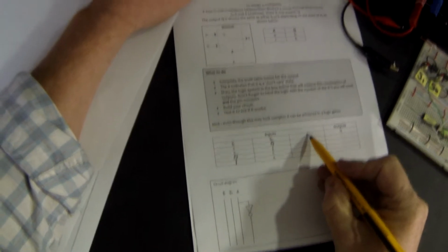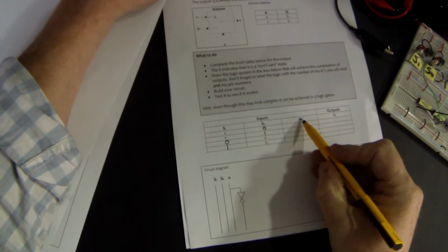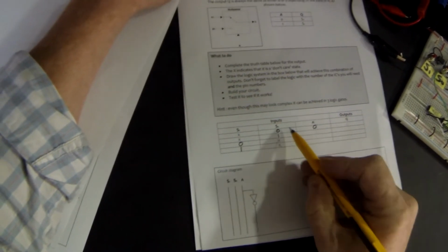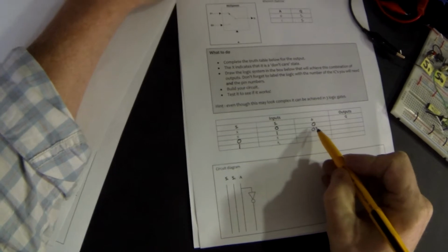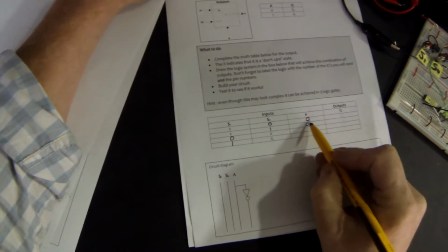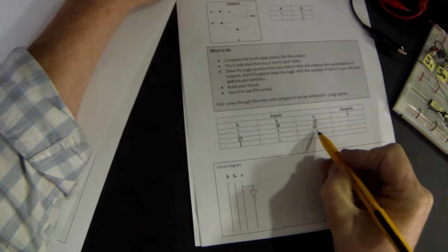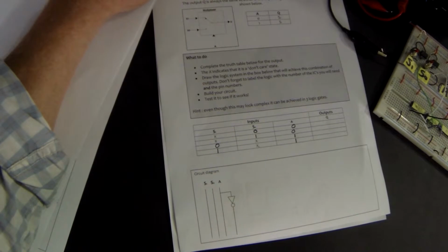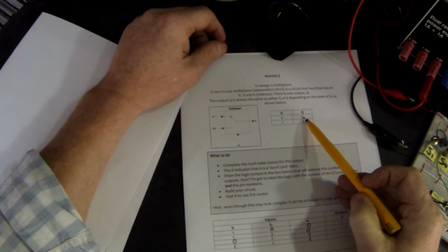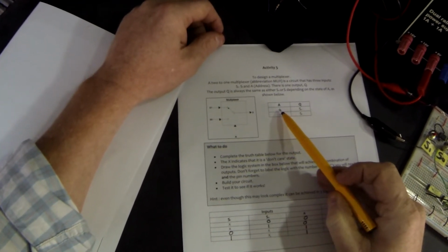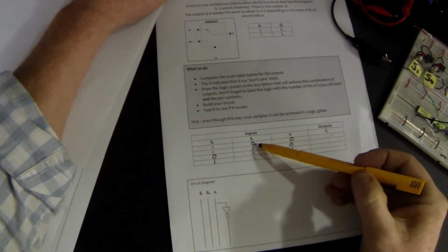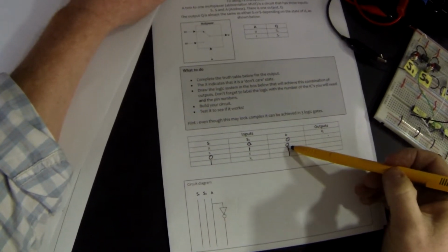Now, A can either be a 0 or a 1. So therefore, let's give it the value 0, and therefore when A is a 0, S0 will follow it, and when A is a 1, S1 will follow it. So, going back to our truth table, we said that Q is the same as S0 when A is a 0.